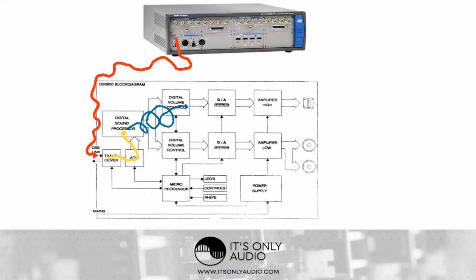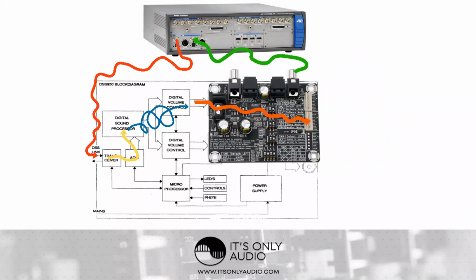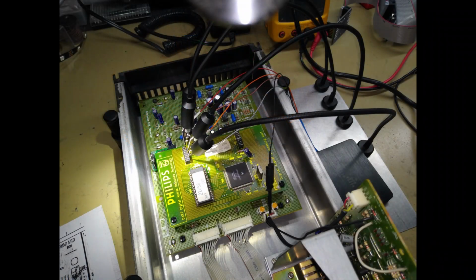The DSP processes it. And then instead of looking at the analog output of the speakers or even the line level DACs, I'm taking the I2S signal out from the DSP before it goes to the SAA7350 DACs, and we're converting it using a Wolfson 8804 chip back to an SPDIF signal and sending it back in the digital domain to the Audio Precision. So now we have isolated every analog component. We're essentially just looking at a digital in, digital out signal, which means that we're only looking at the DSP.